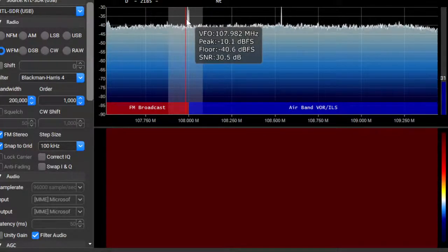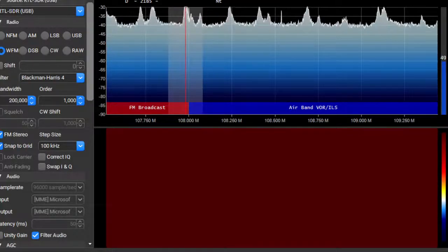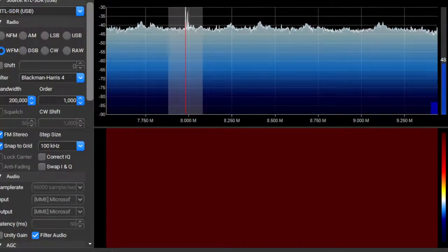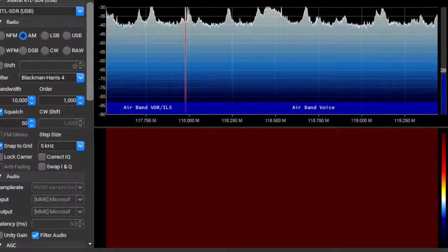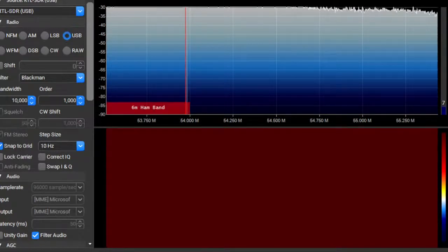So I'm going to put the power back one more time just to demo this. All right, now as soon as I put the power, you can notice that huge spike in signal. Now we're using a 27 megahertz crystal, which means that we should receive the signal also at 54. So let's go 53 now. I'm saying 53 because of these points here. So the signal should also be here.